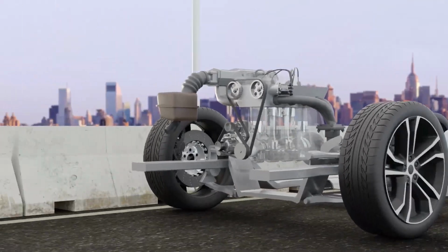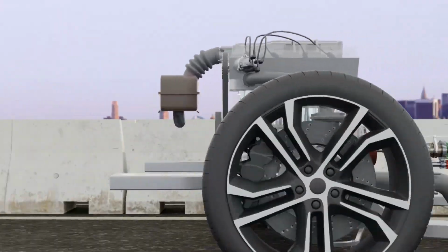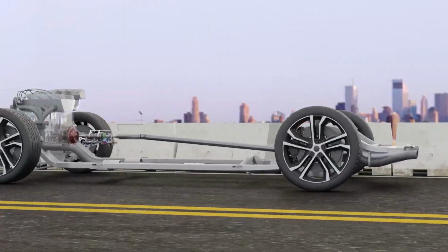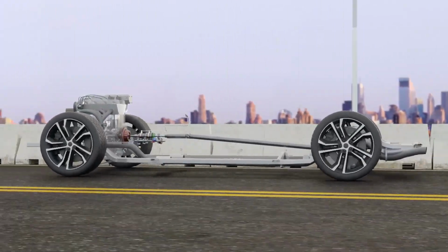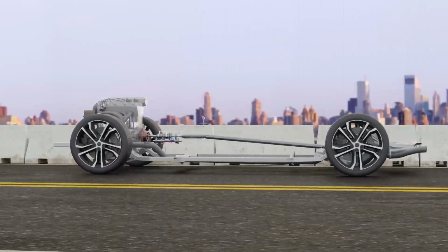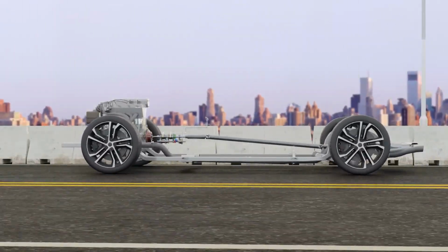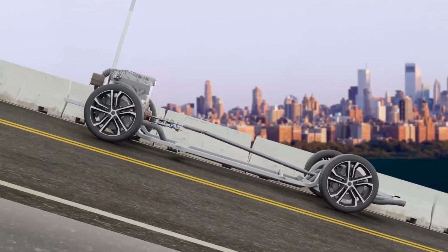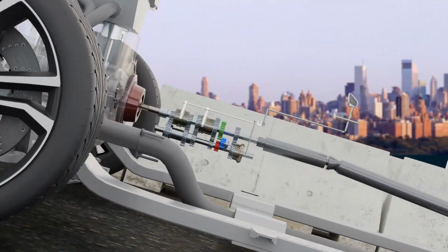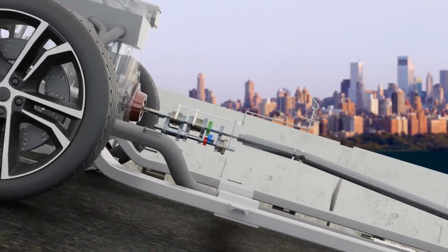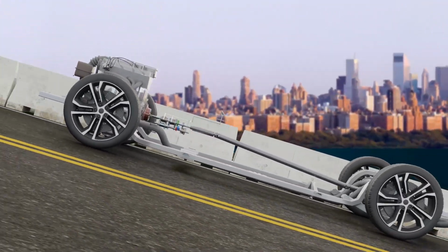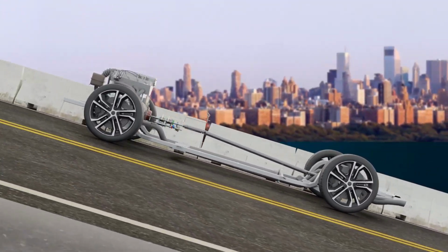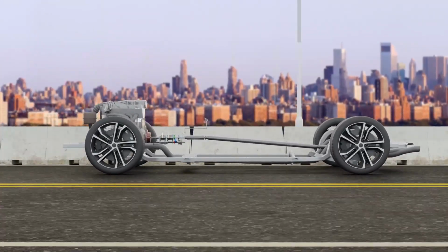The power generated by the engine flows through the transmission before it reaches the drive wheels. The basic function of the transmission is to control the speed of the torque available to drive wheels for different driving conditions. For example, if you want to climb a hill, you need more torque. By reducing the speed at the transmission, we will be able to achieve higher torque for the same power input, where power equals torque multiplied by speed. Conversely, if the torque demand is low, we can increase the transmission speed.